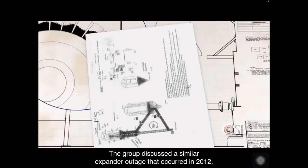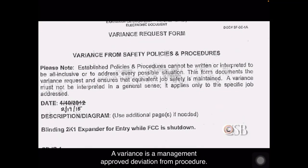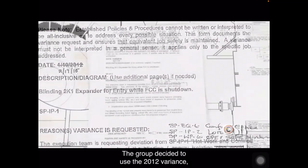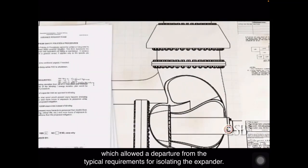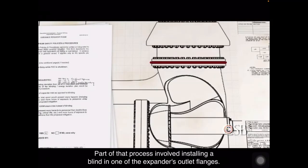The group discussed a similar expander outage that occurred in 2012, for which the refinery had developed what is called a variance. A variance is a management-approved deviation from procedure. The group decided to use the 2012 variance, which allowed a departure from the typical requirements for isolating the expander. Part of that process involved installing a blind in one of the expander's outlet flanges.